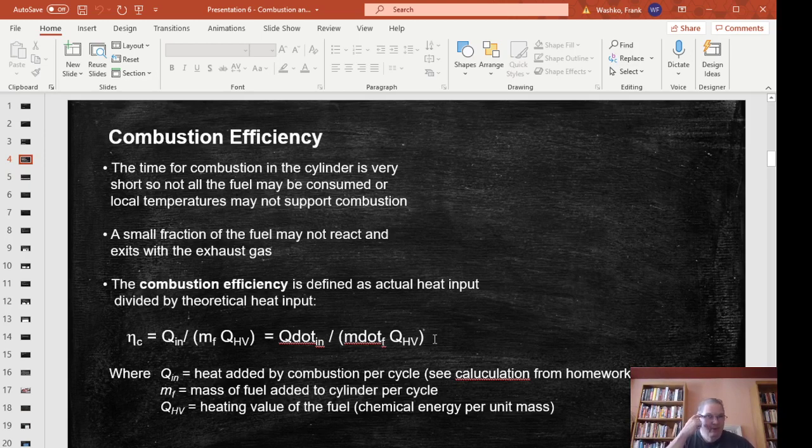So that's part of the reason that you need this atomized. You can't wait for it to just burn over some long amount of time, and then it slowly increases. You need it to actually combust quickly in order for this thing to function properly. For it to combust quickly, you need to have it pretty well atomized in there, and uniformly atomized.